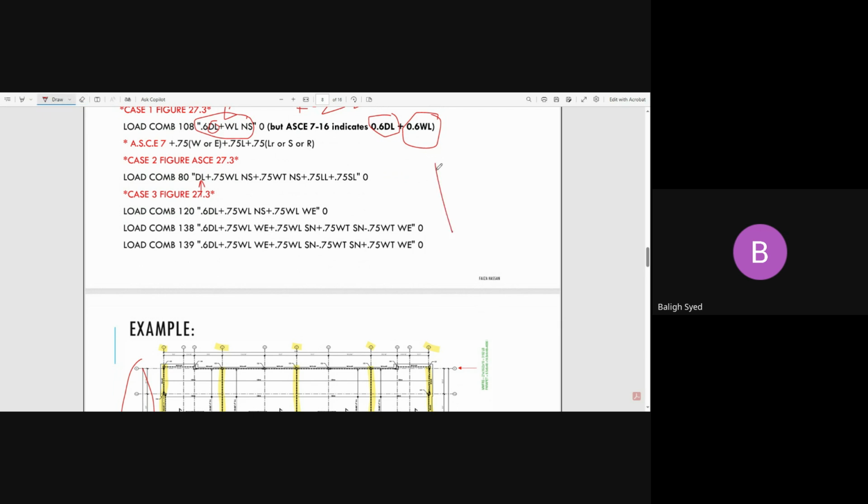You have this structure, right? You solve from both directions. Whatever you design your shear wall for, the wind pressure from this direction and wind pressure from this direction, but you don't know how you will get the worst uplift. So you have to add the wind torque with this load combination. So there will be 4 wind torques.